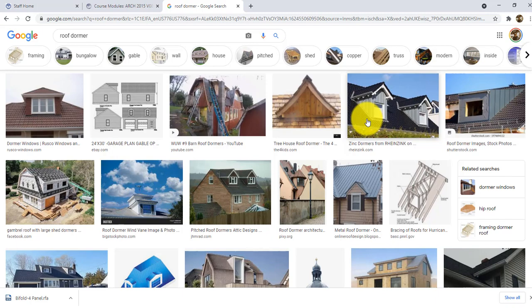The only difference is that you're going to go over to the elevation and create a different level for the base of your walls, so that there's some place that you're starting with those walls. Now what I'd like to move forward and show you is how to create this kind of dormer, something that has the roof split and it slopes up, but the wall goes all the way up to it. There is no roof in front of it right here. So it's still a dormer, but it's just a dormer with the extension of this wall.